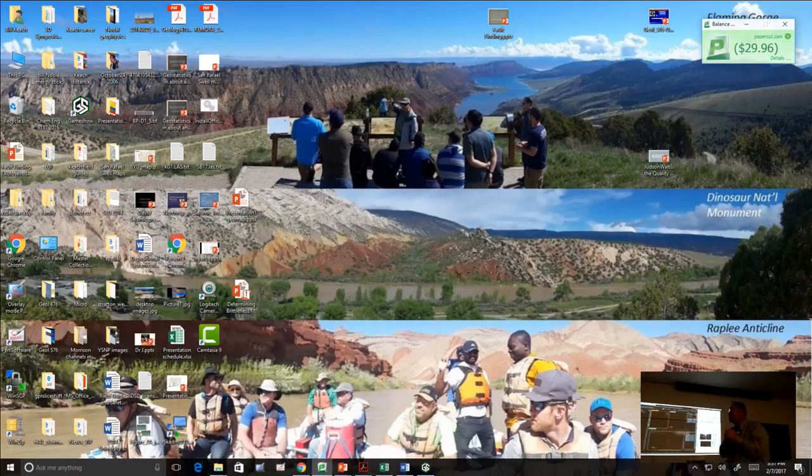So I want you to choose geophysics. It's right on that bar there, but let's just do that one first. Yeah, you got it. Very good. And there's an up arrow right here for uploading, load data to session. So we're going to click on that. I missed something. You're in horizon interpretation.